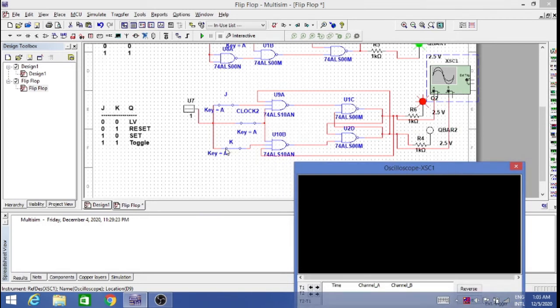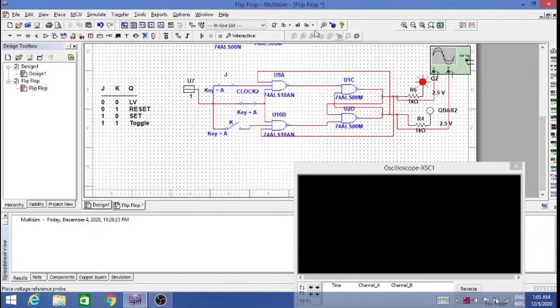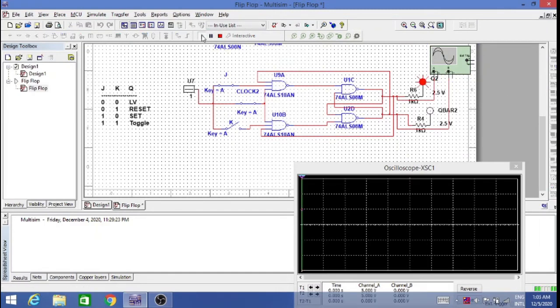Let us see what exactly is happening over here. Let me trigger the circuit on J and K. I've triggered it, and you see the red line: J is high, K is low. Now I'm opening J and putting K. You can see J is coming low, the lower one is K, K is high and it's moving. Now I open both, so it will be 0 0, same state.